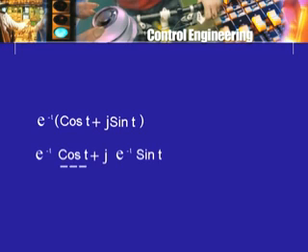If I had only cosine t, or only sin t, then what is it that I have? I have a simple sustained sinusoidal oscillation, and the angular frequency for it will be simply omega equal to 1, because it is cos t, not cos omega t. Therefore the corresponding frequency is 2 pi f equal to 1, so f equal to 1 by 2 pi hertz. But I don't have that, I have that multiplied by e raised to minus t. So this is said to be a sinusoidal function, either cosine or sine, the common name for it is sinusoidal function which is exponentially damped.